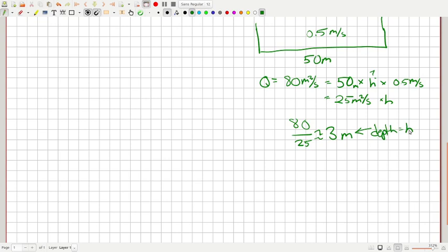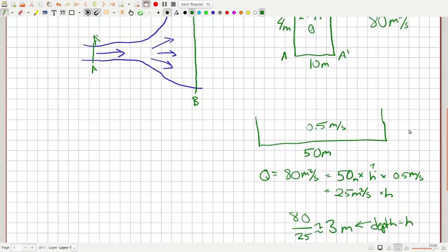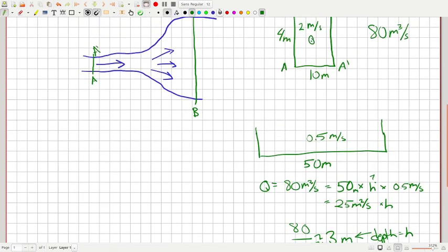So there we go. That's the concept that we have right here. This is continuity, and you can use it to try to understand what relationships between different flow and different zones in the river might be. And one last piece about continuity is that it's more than just water. I'll put this in gray because it works for sediment too.